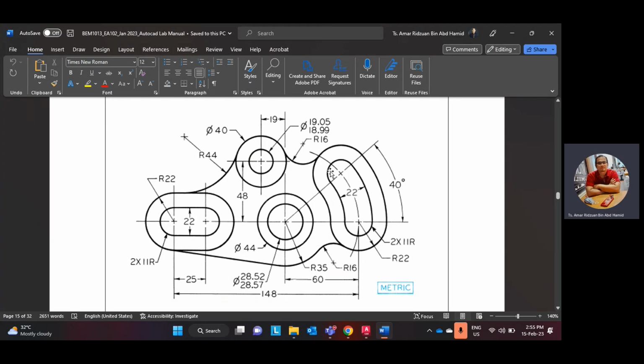Okay, then we can draw the same here as well, because actually these shapes are the same as these shapes. All right. But we need to know this point. So this point is actually referring to your first lesson. We need to find this point. So what's the command? Shift at 60, shift angle 40, right? So remember, this is our first lesson. So shift at 60 because 60 is the distance, and shift angle 40 because 40 is the angle, okay?